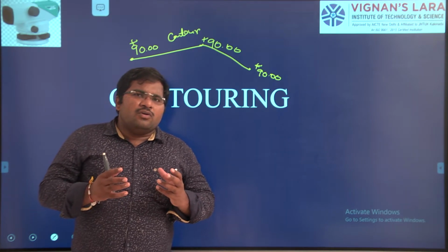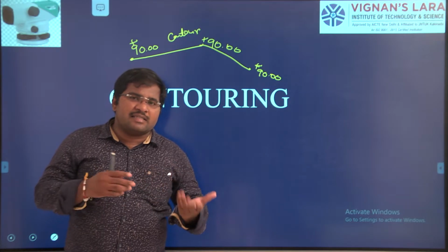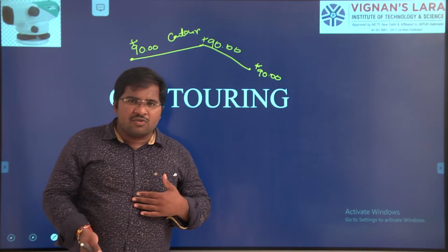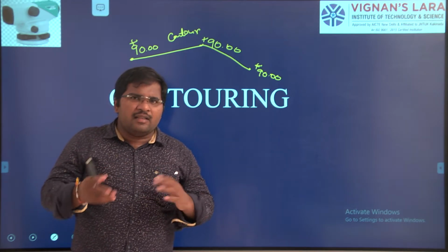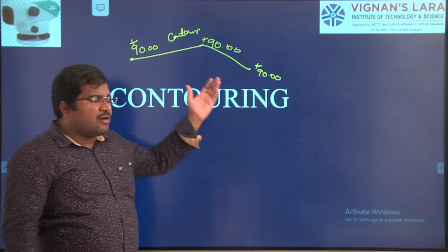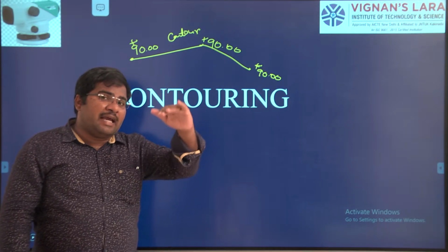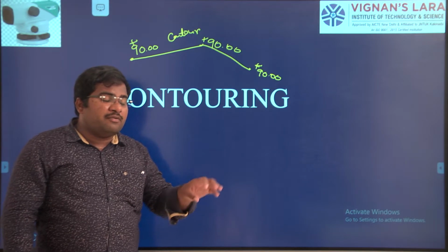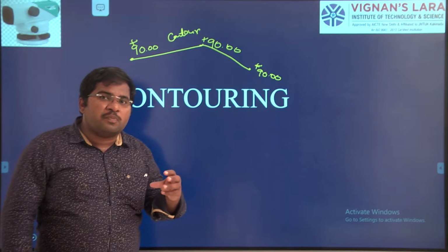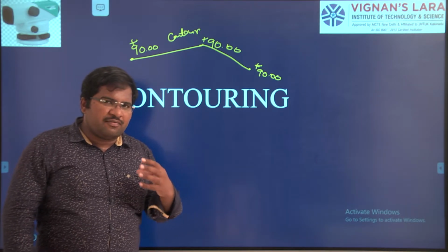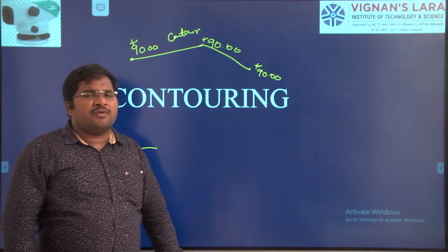So to establish those mountains, hills, valleys, ridges, where a stream is going, where the height is more, where the depth is more, to locate all these things, we draw the contour. With the help of the contour, we locate on the map which point is at a higher level, which is at a lower level, which is a mountain, which is a lake, or which is a valley. Those features of land we get to know by this method of contouring.